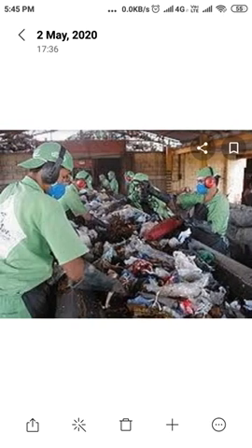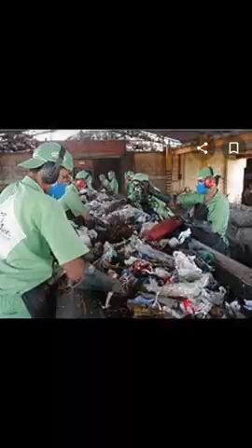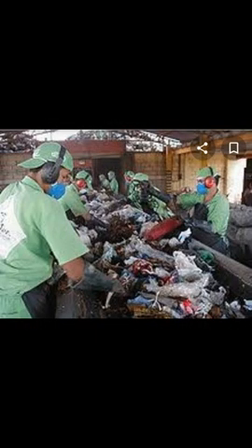If you see the hand sorting, that is nothing but removing the solid waste manually. In this manual separation of the solid waste, the components can be separated at the source, where the solid waste is generated, at the point of the transfer station, at the centralized processing stations, or at the disposal site. The number and the type of components sorted depend upon the locations and reuse market.